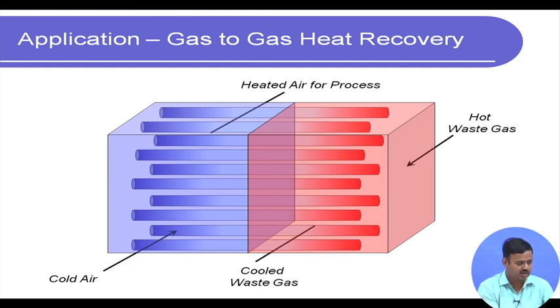Okay. Just to let you know, the plate that is separating the two sections is many a times called the splitter plate, and as we will see later, the orientation of the splitter plate can be changed. It can be kept perfectly vertical so that the heat pipes are horizontal, or it can be inclined to give some inclination to the heat pipes, and as we will see, the performance of a heat pipe is a strong function of its inclination as well as other geometric parameters. Okay.